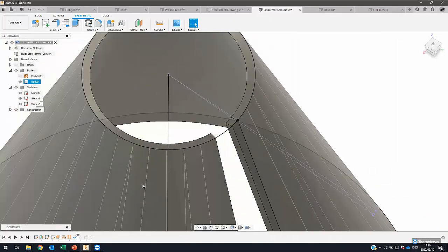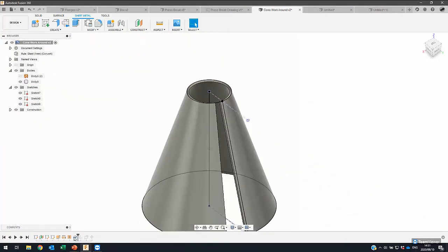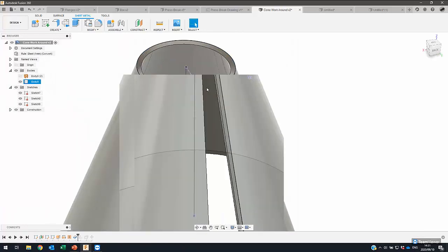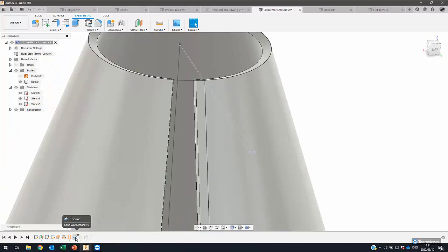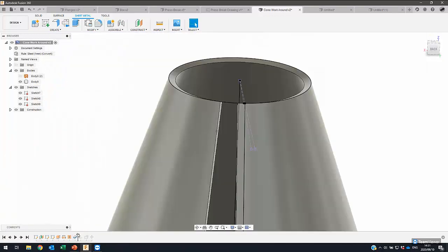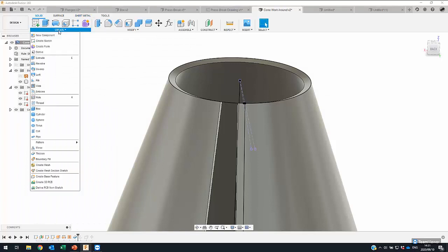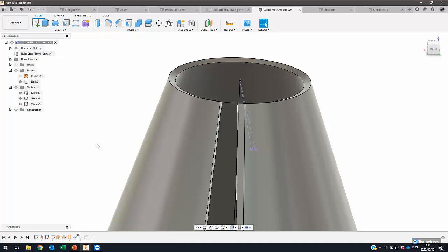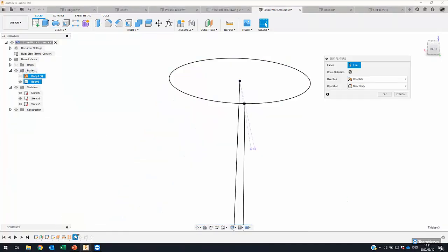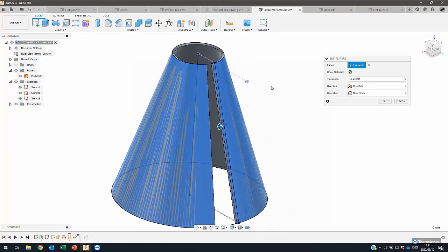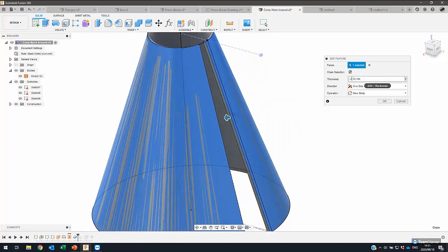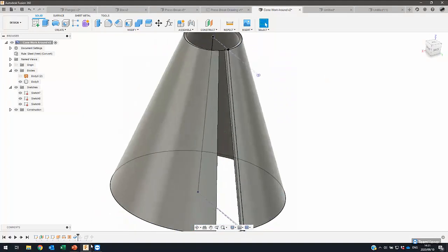So in this case, I think I used quite a thick material, probably about 5 millimeters. And now with that material being offset, we're able to go to the Create panel and then convert to sheet metal. Now before I do that, I'll explain why I used the offset option here. Under your standard solid modeling, you can create a thicken or an offset, and what that does is it takes that surface and gives it a uniform thickness. That's one of the rules mentioned earlier, that it has the same thickness throughout the part. So here we can see the thickness was 5 millimeters.